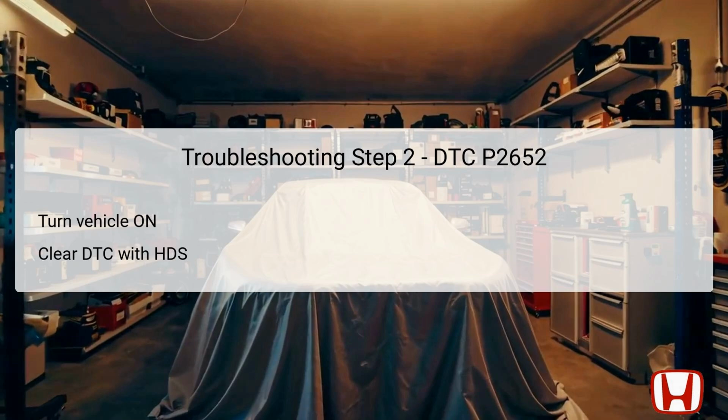After clearing the code, turn the vehicle to the off or lock mode, and then back to the on mode to recheck the system. Following this, access the VTEC test under the inspection menu using the HDS. This step is important as it assesses the state of the VTEC system under defined conditions, allowing for accurate diagnostics.